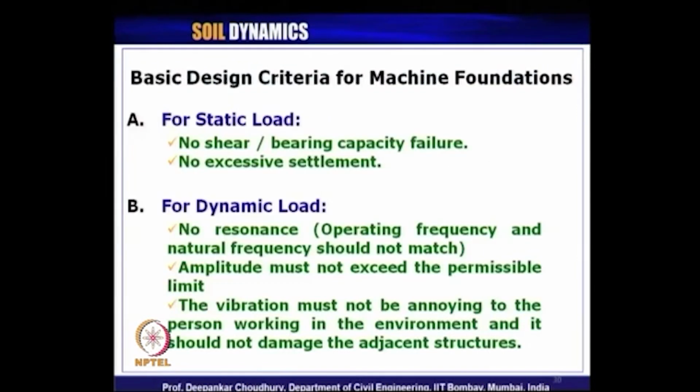Okay. What are the basic design criteria for machine foundations? First one, of course, these foundations have to be designed for the static load. This foundation should be well designed to take care of the static loads coming on the foundation. So, what are the checks we do for static loading? We have to do the same thing here, that is, no shear or bearing capacity failure should occur.